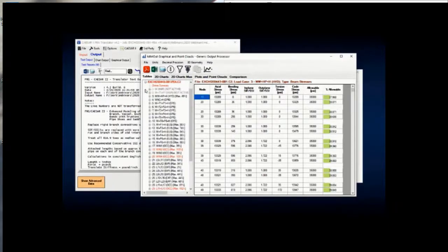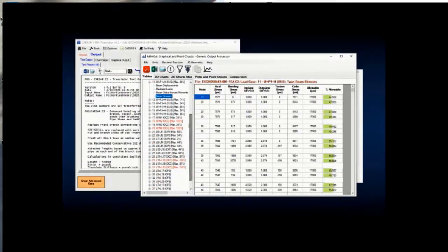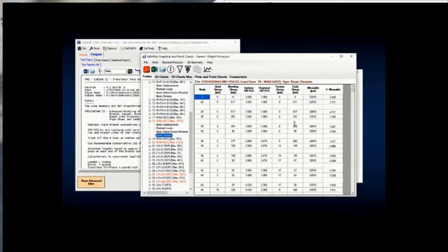If I expand the translated model, we have solved the problem with the sustained cases. But we do have occasional cases that are now overstressed. The distribution of loads around the model, due to the improved flexibilities and SIFs, has shifted the stresses into different locations, which now have overloaded the occasional cases. Now I want to find out which nodes are overstressed for these cases. Again, I'm going to sort descending and see what 858 is.